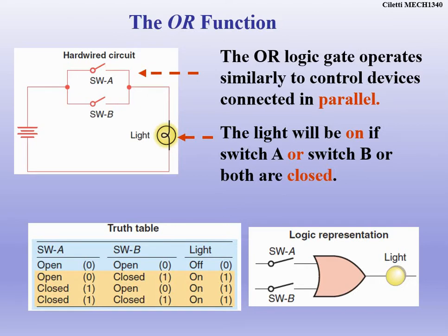Notice an OR looks more like a branch. I've already mentioned in a previous lecture, if we're going to go in series or in parallel, how series is more like an AND gate, parallel is more like your OR gate. Remember when we talked about series circuits, it should all make sense. If you cut the series circuit, nothing's going to turn on because everything has to work together. Remember, if we had a parallel circuit, since it had multiple paths for current to travel down, if we removed one resistor, it didn't change whether the circuit worked or not.